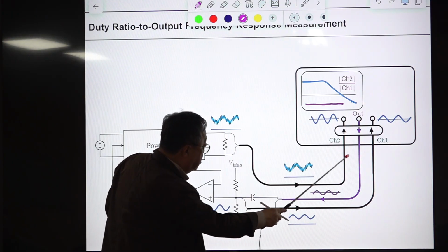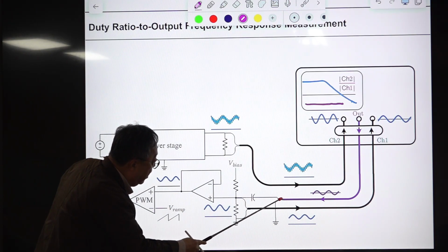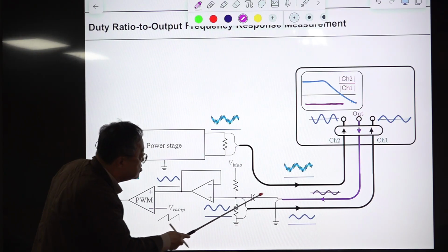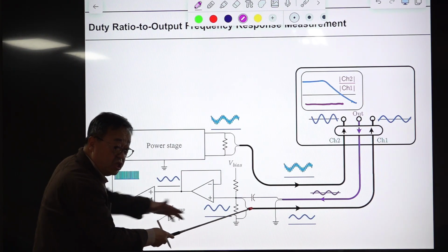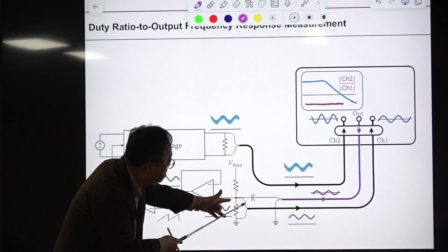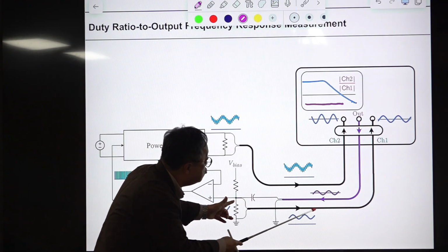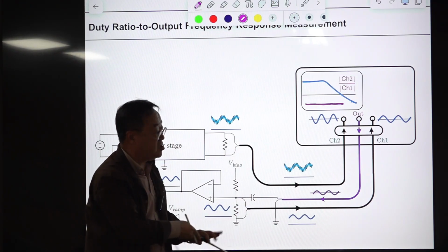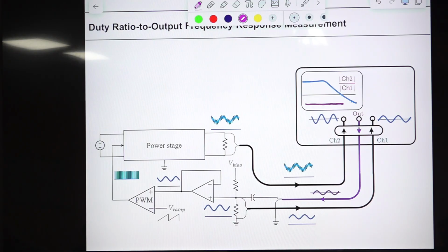Okay, that signal is generated, and here that signal is passed through this, a DC blocking or AC coupling capacitor, and this input voltage is connected to this. So this is input voltage sampling. Maybe this is the VS sampling. Sampling here is different from the sampling in a discrete time system.